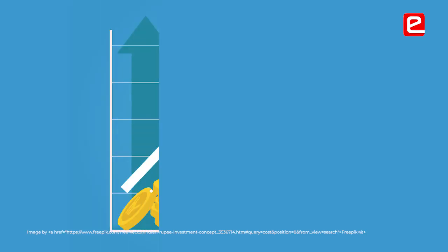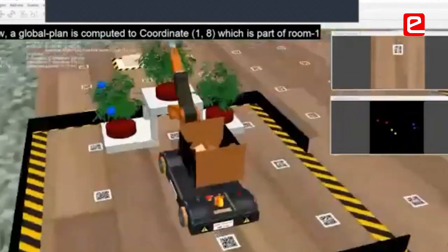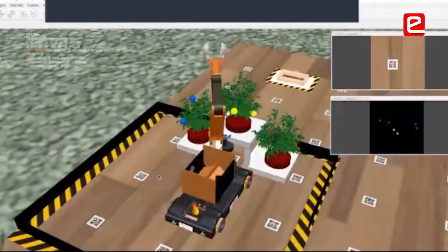Could you tell me what the limitations of your design are? The payload would be one big consideration for our robot's design, and depending on how the payload changes, the torque provided by these motors would also be another consideration. So if the payload is heavier, we would need higher torque motors, which would cost more, and also for the encoder's resolution, we might need to opt for a different sensing technology other than optical ones, maybe a capacitive or a magnetic sensing technology for these encoders.